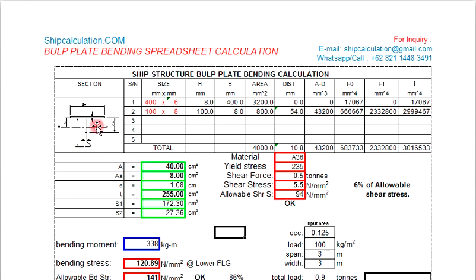This is the deck loading, the deck and then the bar plate, the scantling one. For the deck one, you can just change the width based on the spacing and then the thickness. The thickness will be generated automatically, even the size of the bar plate. So let's say the thickness is 12. This one will be changed to 12.